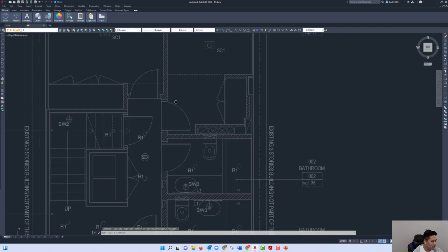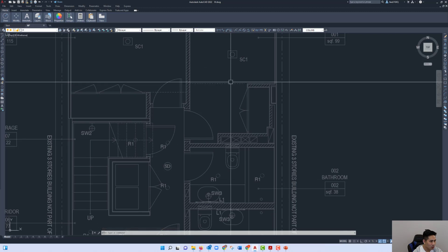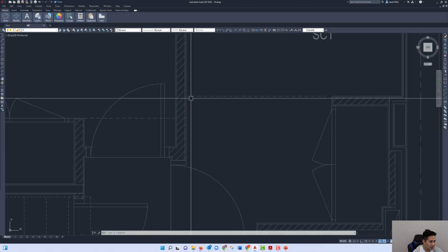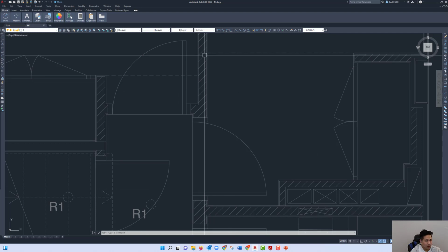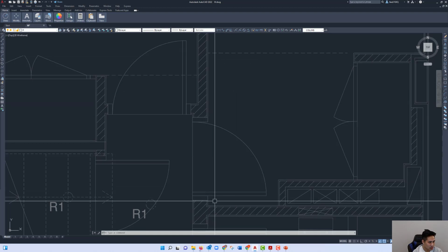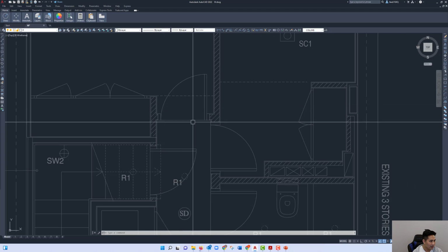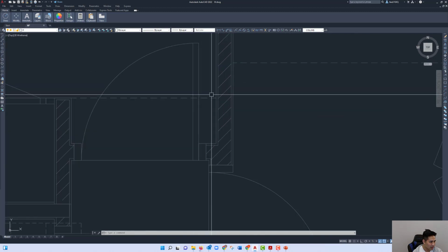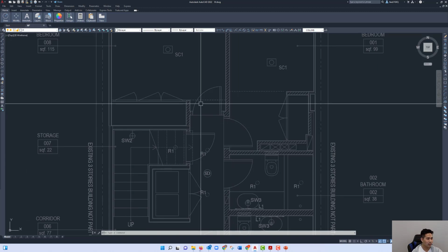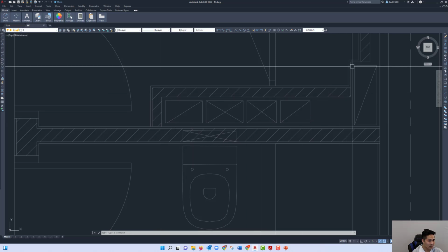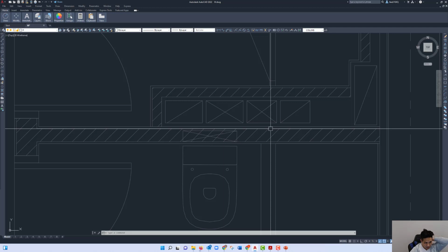So in this example, what the architect decided to do was to give us a small drop ceiling portion where we can run ductwork perpendicular to the joist, and that drop ceiling is represented by this dotted line here. So in this case, the drop ceiling would be this portion here. And also they gave a small drop ceiling right after this door opening of this amount right here. So we're going to utilize this in order to run some of the ductwork. And this is the shaft that the architect gave us where we can route some ductwork up to this floor.